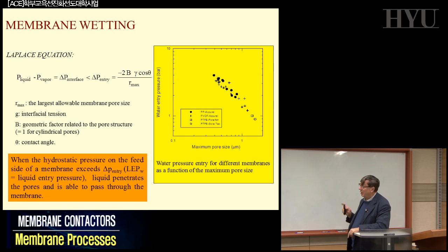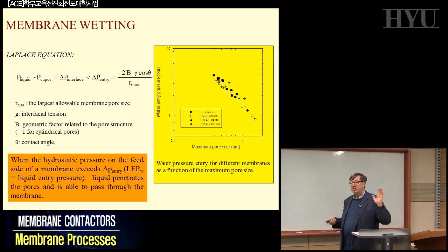Everybody working in membrane contactors in general, and membrane distillation particularly, has to be very familiar with the Laplace equation. The Laplace equation is telling you that when I'm talking about a hydrophobic system, no liquid will penetrate, which is the relationship between the possibility to penetrate or not penetrate.